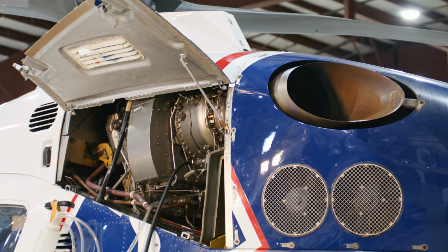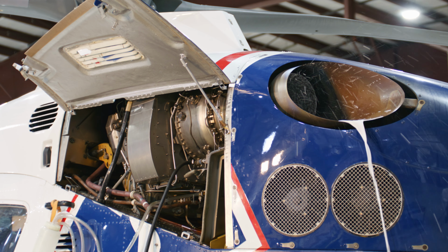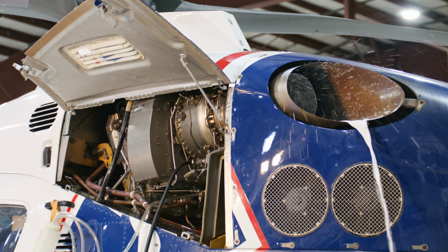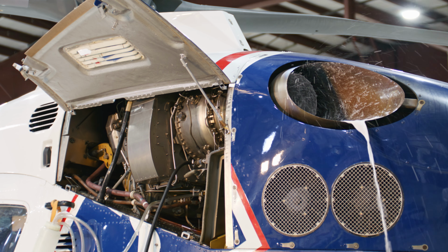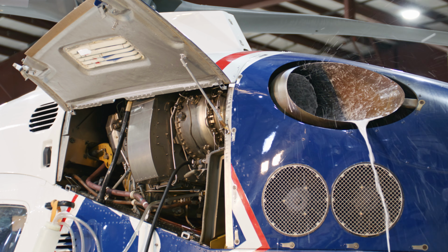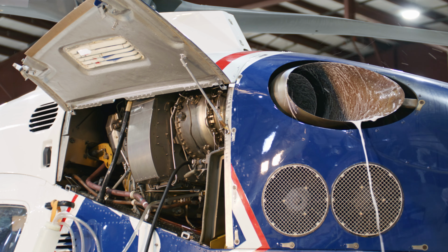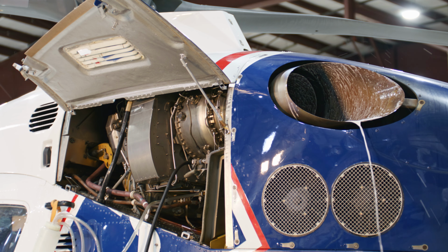4 liters of cleaning mixture injected at the maximum rate of 8 liters per minute requires 30 seconds of injection time. Have you ever verified the flow rate of your equipment? For those with large washing and rinsing tanks, how do you verify the quantity that was delivered? With the known delivery rate, we can verify the injection quantity.